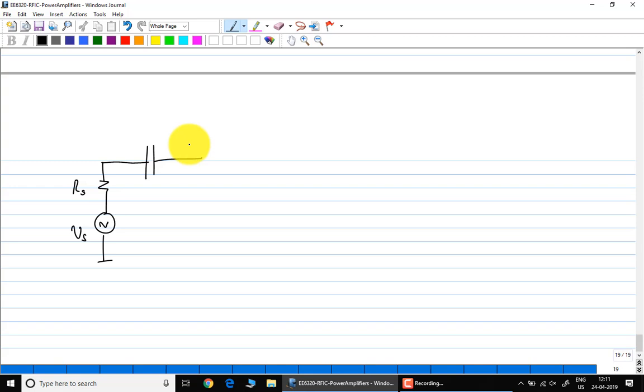Receive antenna will normally receive a whole bunch of things. It will receive the direct signal, it will receive signals reflected by a whole bunch of reflectors. You just cannot predict. Okay? What you can do is you can predict the approximate behavior, right? That you can do. Because remember, if you had an omnidirectional antenna, for example, you are radiating out into a solid sphere. So typically it will go as 1 over r squared, the power. But the actual power which you receive at the receiver will not go as 1 over r squared. Okay, it may be much lower because of reflective paths. Okay, because of fading. It's called fading.